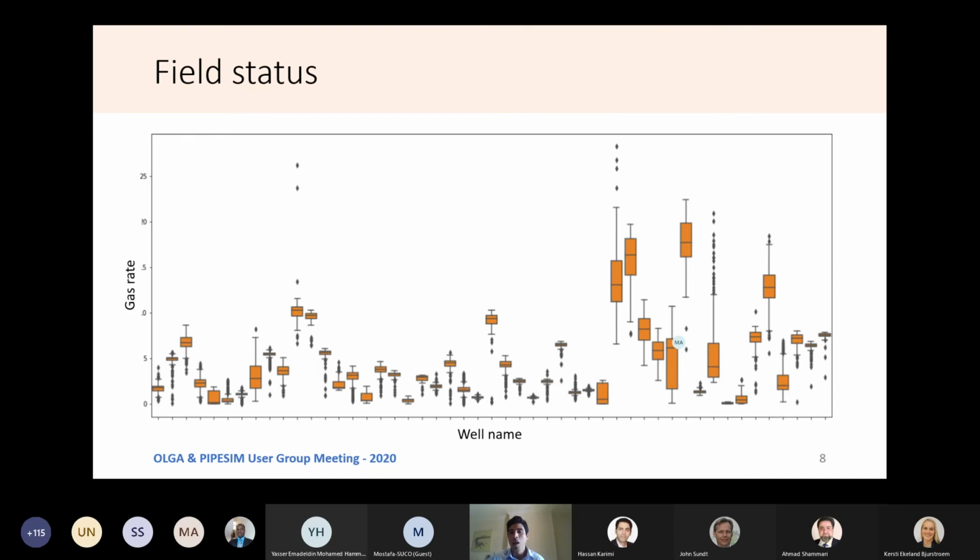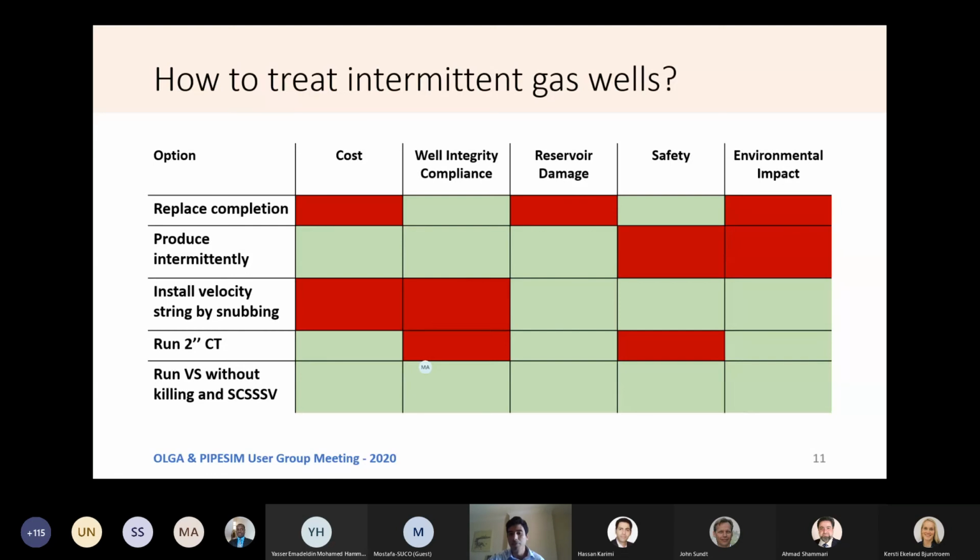Our field is an onshore gas field in the depletion phase, with low rate of success in some of the new wells as we see here. The majority of production is coming from new wells. The area shaded with red contains wells that are described as old wells with 5-inch completions. Around 10 of them are suffering from liquid loading issues. By the way, the chart represents the distribution of production data per well over the past 2 years. Our champion for today is the one highlighted in red.